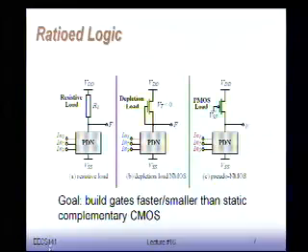So over the years, we've gone to a number of different ways of implementing the load device. So instead of using a resistor, I could use a transistor as a load. But in this case, you can see that these resistors are not connected to the input. So the input capacitance I see is still only a single NMOS device. Okay? This thing only acts as a load that helps us to determine where the logic levels are going to be sitting.